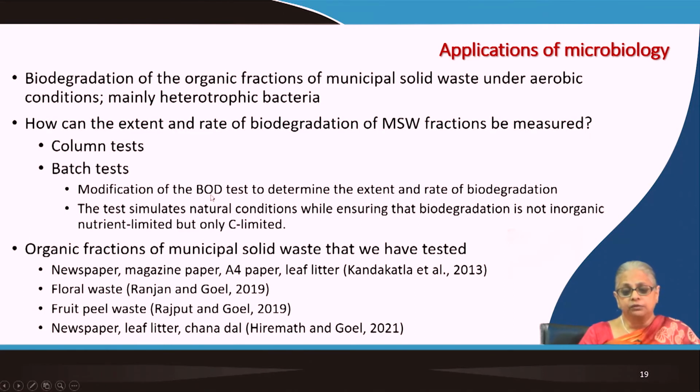So like I said, it's a modification of the BOD test, and we're doing two things. We are measuring the biodegradable fraction, and we are measuring the rate at which biodegradation is happening. The test simulates natural conditions just like the BOD test, with one major difference, and that is we are ensuring that the system is carbon limited only, that the microbes are growing under carbon limiting conditions, and all other inorganic nutrients are there in excess of the microbial requirement.